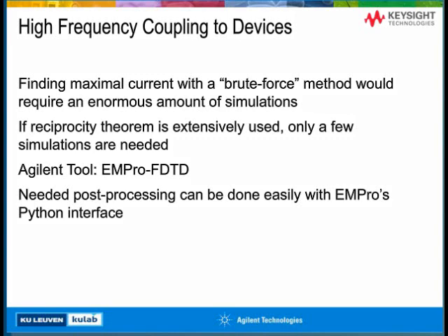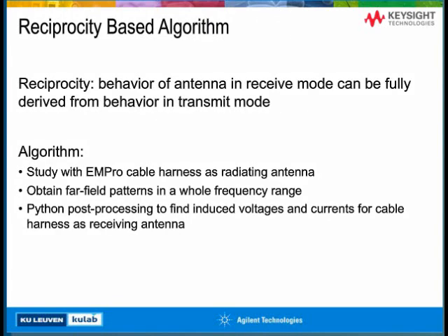The tool that we used was again EMPro and the FDTD simulator, and the reciprocity theorem was applied by post-processing that was done in EMPro's Python interface. Now, what's the reciprocity-based algorithm? Reciprocity means that the behavior of an antenna, or an unintentional antenna here, like a cable, in receive mode can be fully derived from its behavior in transmit mode.